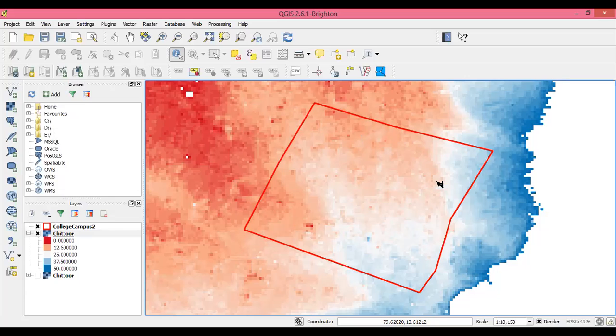That could be a representative maximum length of travel inside the watershed. So that gives you your L, or the maximum travel distance, and your S, which is the slope. Now if you put it into your Kirpich equation, you know the slope, you know the length of travel, you find out the time of concentration.